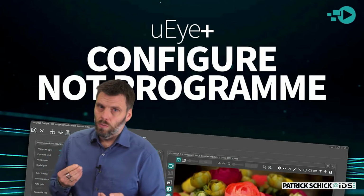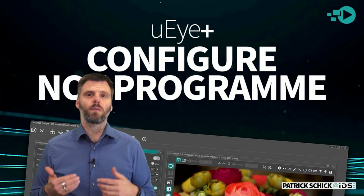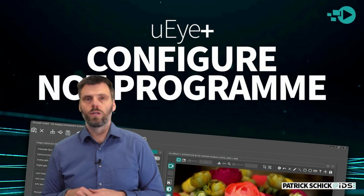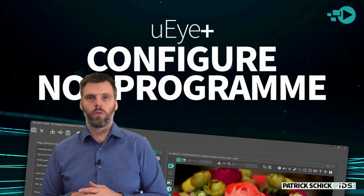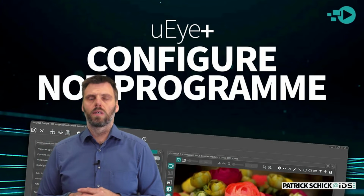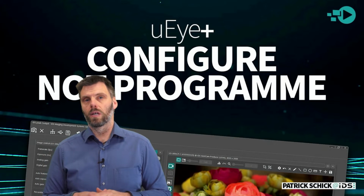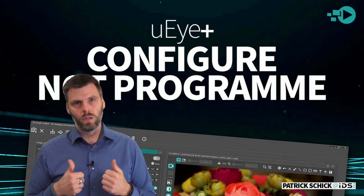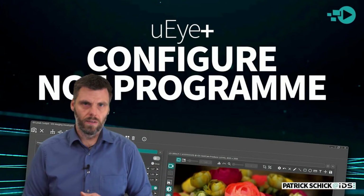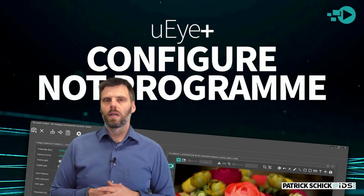But today I do not want to show you only the functions and features of the cockpit. I would like to give you also a hands-on on how to set up a good color representation of your camera so that you can directly reuse it in your machine vision application. So we do a white balance, we configure the right dialogues for doing the white balance, and we store the white balance in a so-called parameter set so that you're able to load it in an upcoming application.